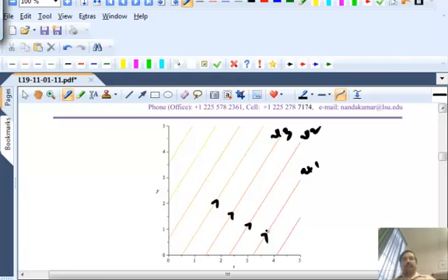So what would be the x1 component? And what would be the meaning for alpha? If this is alpha, then the x1 component will be u cos alpha. The x2 component will be u sine alpha. So from that you know that this also represents uniform flow, but not in the x-axis, not in the y-axis, but at an angle alpha. So you now give that meaning to this parameter alpha in the expression that was given to you.